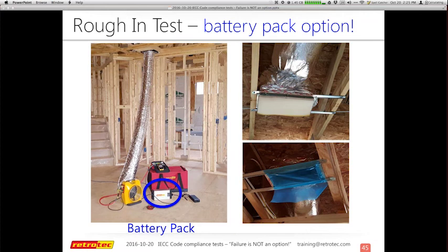So here are some of the options, though, for sealing your ducts, because you can use the traditional duct mask, the sticky tape, but you can also get some foam and just push it inside the duct opening. It makes it a lot easier to reuse these and go around.